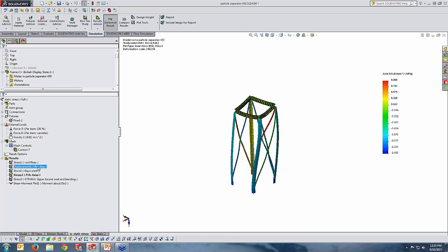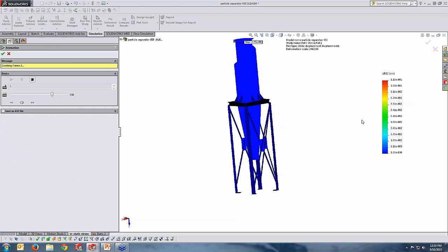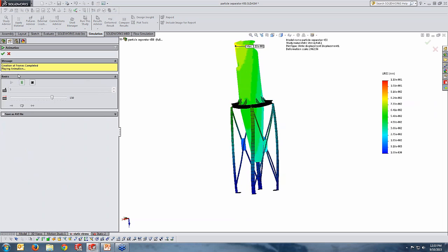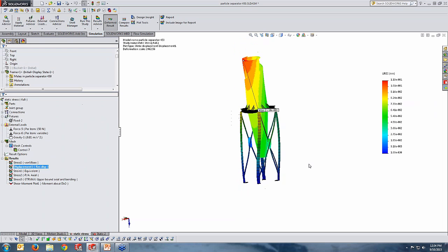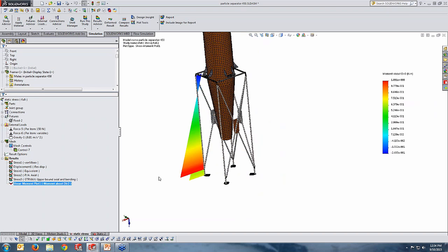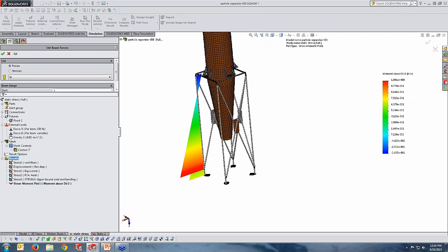For the displacement, you can see the whole displacement on the structure, and anytime you like you can animate it, understanding the magnitude and distribution of the displacement in your design. And the last thing is, again, exactly what we have experienced before: creating beam diagrams, like the moment about direction 2 on that specific leg, and looking at the values and direction of the change, and the location of the change. And at the end, you can list result force, beam force, or anything else as you might require.